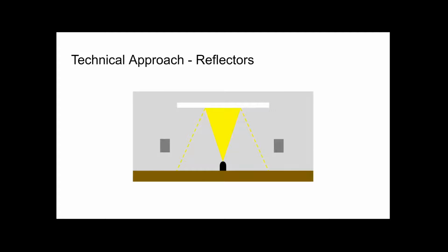We used a single emitter design with a reflector so that we can get a symmetric pattern of light intensity around our board. If we had decided to, instead of using a single upward-facing emitter, use multiple outward-facing emitters, we would have had higher and lower intensity regions. The goal of this design was to make everything uniform so that no matter where the beacon is around, it'll still get a uniform intensity.